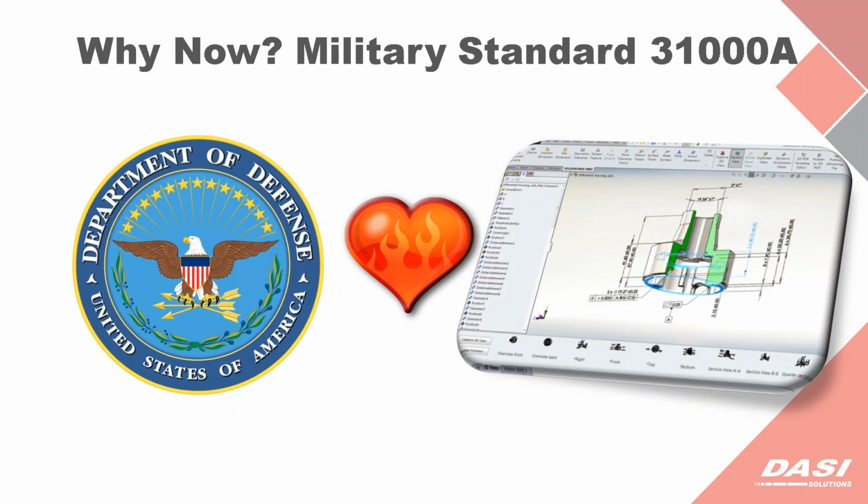So why are we talking about MBD? Why has MBD suddenly come to the front of everybody's attention? About 5 years ago, I think it was now, military standard 31000A was released. I think it was about 2013 or so, in which the Department of Defense outlined exactly what they like to see when they're having 3D CAD models with all the information on it. In some cases, different contracts will actually see this pop up as a requirement. So not as a broad spectrum requirement, but you might see it in some cases.